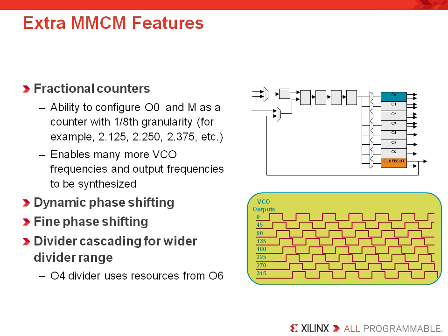Now, one of the nicest benefits is being able to configure the output O on an output basis. This allows you to generate multiple output frequencies from a single input. The MMCM also allows very fine phase shifting of 1/8 granularity. This enables a wider range of frequencies to be generated as well.